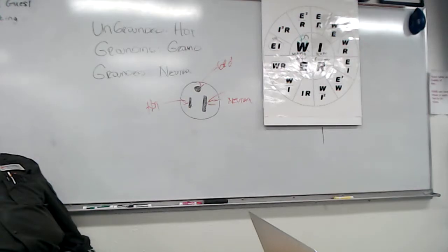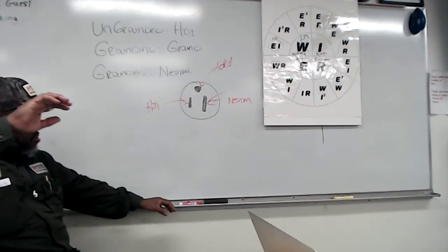All right, so you install a second receptacle in the 2-gang box. A flat volume ring is used. Each of the type NM cables contains a ground. The pigtails to both of the receptacles are number 12. When 2 metal switch boxes are ganged together, what is the minimum depth of each box that can be used? As you can see, the cable connectors are external. Right, so somebody give me the rules for box fill.